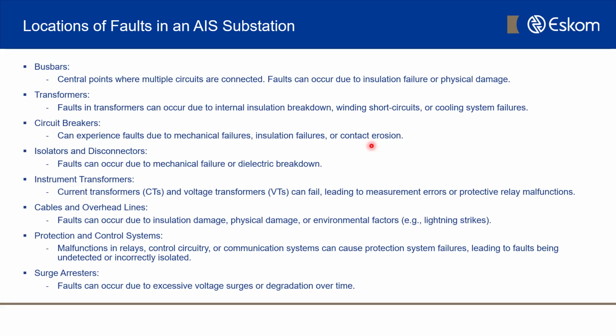It's not actually a fault, it's an operational instance of a circuit breaker when there is a fault. So usually when a fault occurs, the circuit breaker will open so that the system can feel minimal effect, and that causes switching surges, which we will discuss later. And that's why I highlighted circuit breaker in my title for this portion of the presentation.